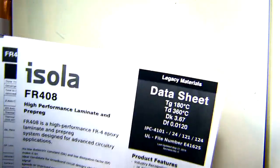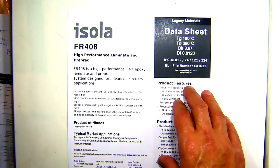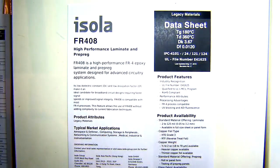Okay, so this is a data sheet for a material called FR408, which is a high performance FR4. Does everyone know what FR4 is? No? You know what a PCB board is, right? The green fiberglass material, that's FR4. That's what you're using to make your boards. You can use different types of materials depending on the performance you require. FR4 is usually good to a few gigahertz.